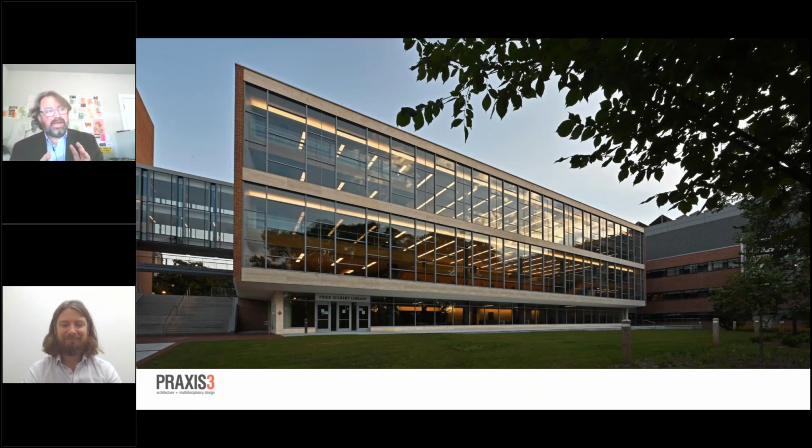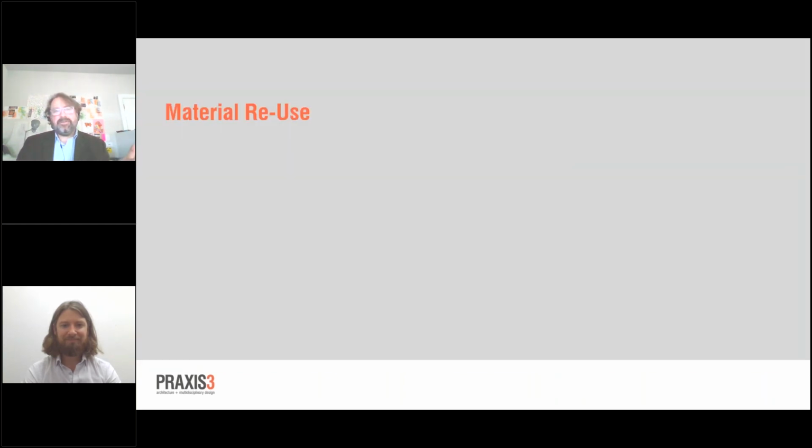We were going to have to replace a bunch of the IG units anyway. So the decision was made to replace this with a 21st century curtain wall, but using the 1953 design as our basis. So we have a little bit more fidelity to the building's original intent, even though this is a new curtain wall, which is the fourth option that I didn't present here. When you're going to address an existing single pane glazed window, you can just take the thing out and replace it with a new window, if that's really what you want to do, which is what happened in this case. So there are lots of options for glazing in these buildings.